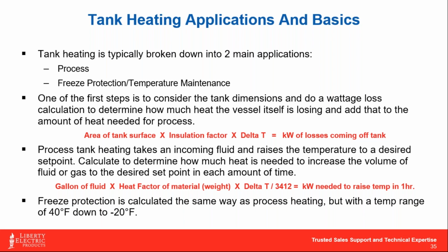for that type of challenge versus, once I've got the tank up to 100 degrees, I just need to maintain it at 100 degrees, where we can get away with using a much smaller heater that, hey, it may take 2 or 3 days to heat that load up entirely. But once you've achieved it, based on your flow rate coming out of the tank, a smaller heater can often keep up with that process application.